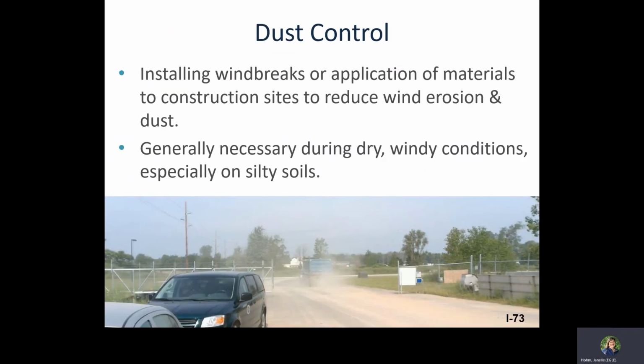Dust control is a BMP which should be implemented when conditions are dry to reduce wind erosion across bare soils. Construction staging is the most effective and least costly solution to this problem. Keeping the amount of disturbed soil to a minimum at any given time helps to reduce the potential for erosion caused by both wind and precipitation.